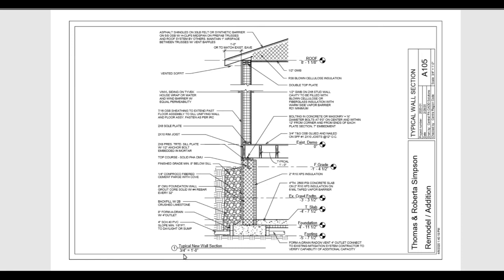In this case it was 3/4 of an inch equals a foot. So for every 3/4 of an inch on the actual sheet, that represents 1 foot. That's basically 3 times larger than the 1/4 inch equals a foot scale. So I can show a lot more detail within this drawing, as you can see, and we'll get more into that later.